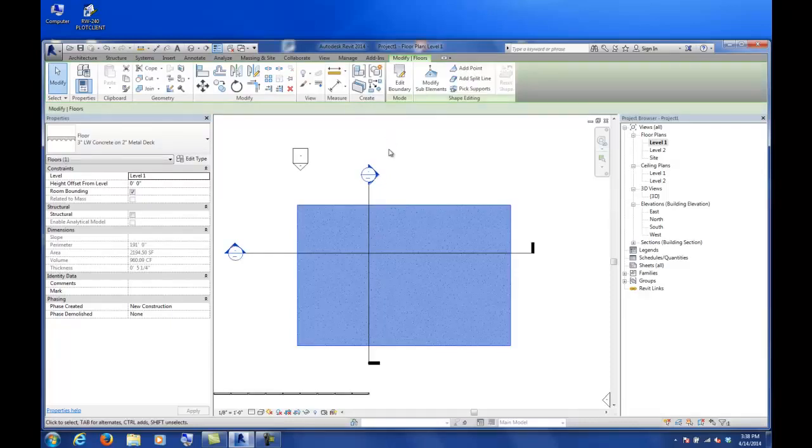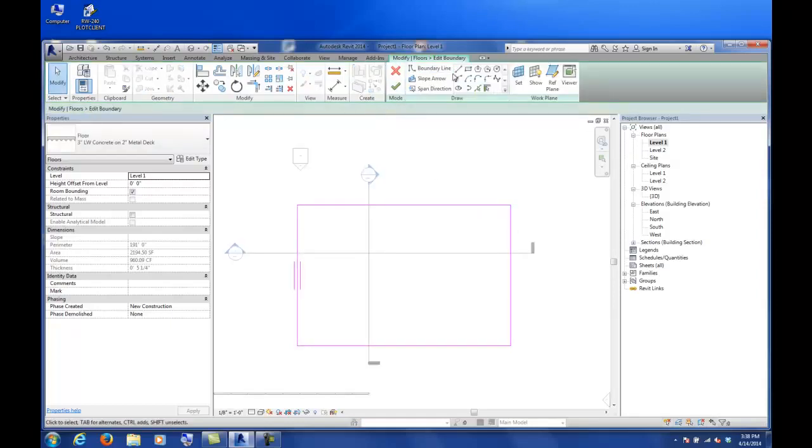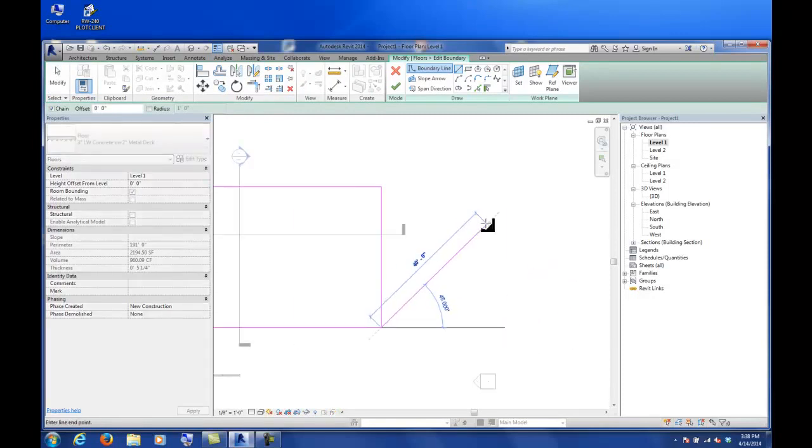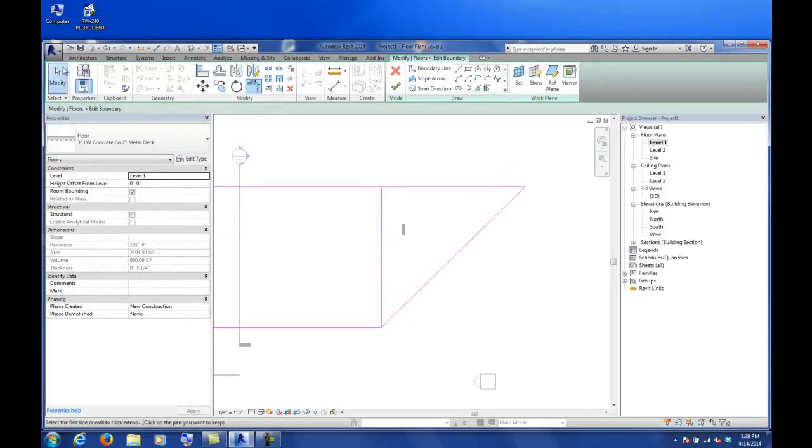And it's only going to go the direction of whatever your boundary lines are. So if for some reason your deck is going 45 degrees or something like that. Yeah, ours definitely is. You would actually need to make sure your floor slab had that angle in it somewhere, because then you can pick span direction and then pick that.